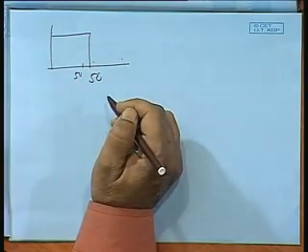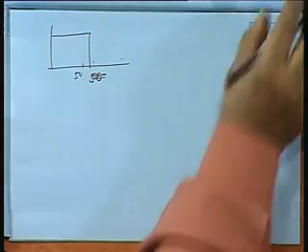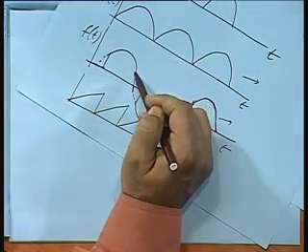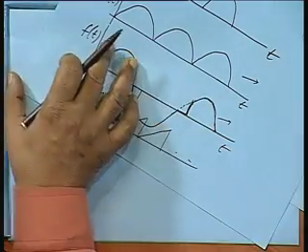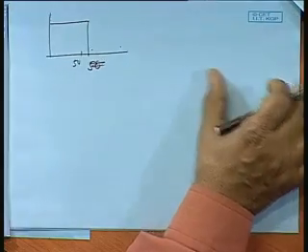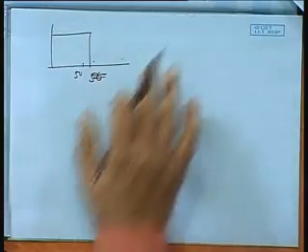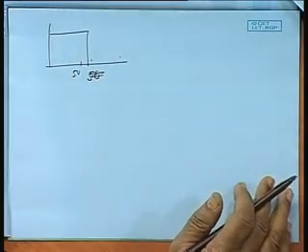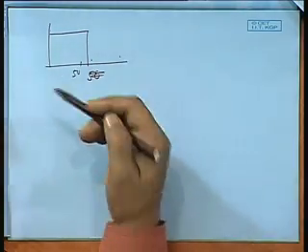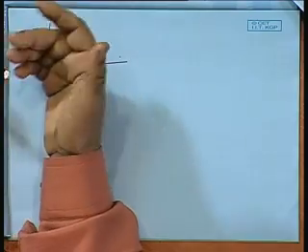So, we should have a low pass filter which will allow only 50 hertz and nothing beyond. The harmonics that will be generated here are 50, 100, 150 and so on. They are all to be suppressed for the protection of equipment. This is a very important area of application of Fourier series in electrical networks.